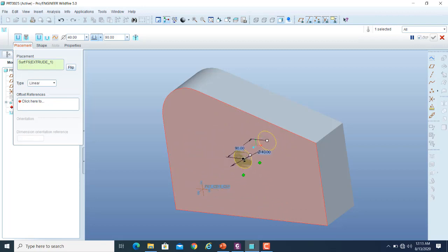How to fix a point on that particular surface? For that we will use these references, these green pick boxes. So hold these grippers, and then these grippers will basically be used to dimension this hole in the vertical direction and in the horizontal direction.